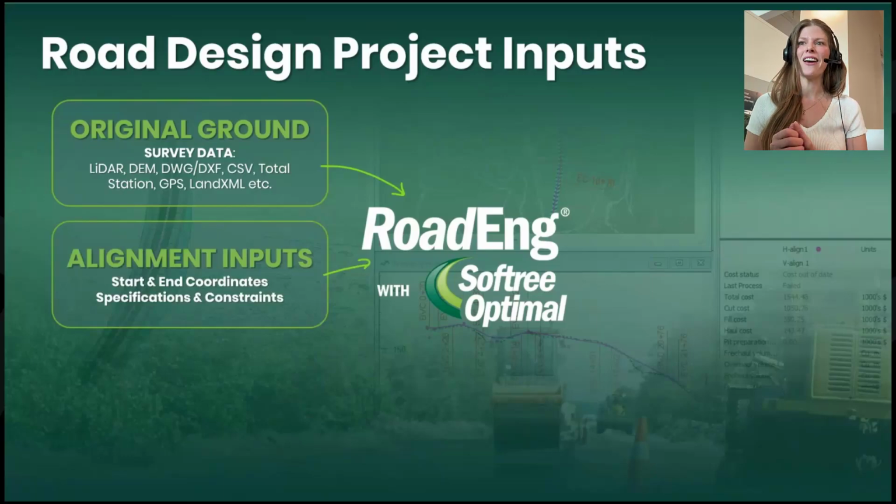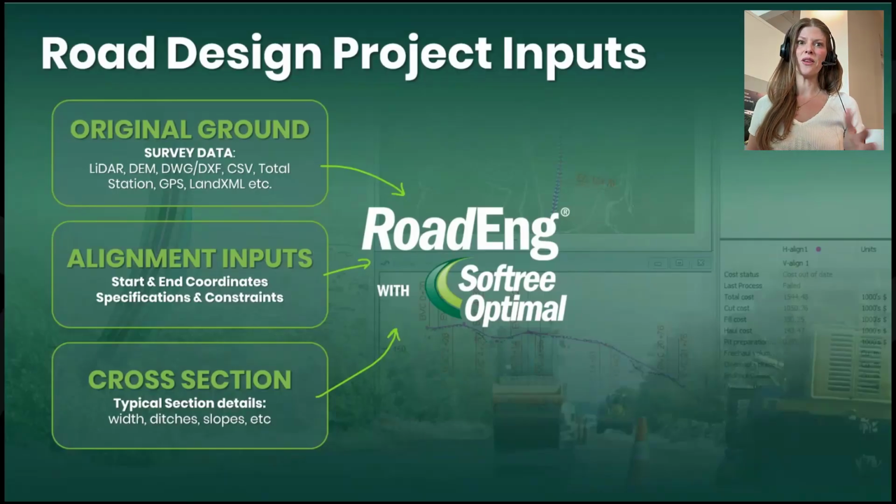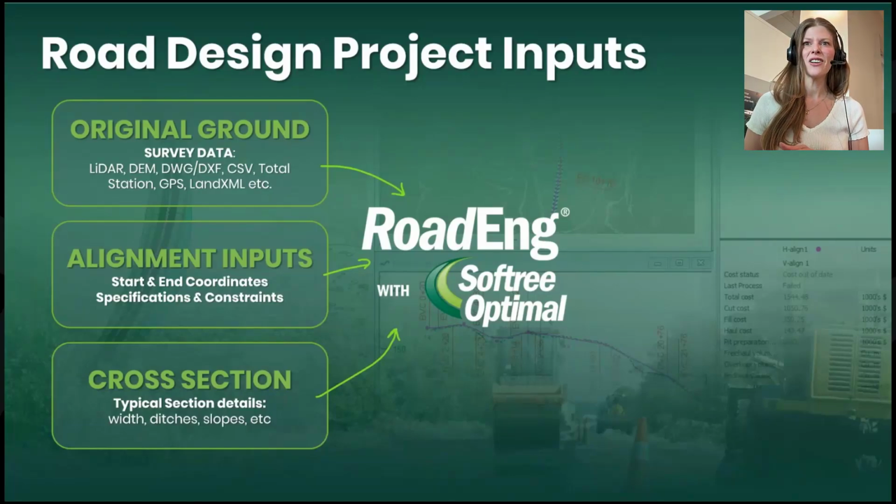From there, the next input, and this one can be as simple or as complicated as you would like to make it, but we need to know some alignment details: your start and end coordinates, some specifications, your design speed, any constraints that you might need to consider. And then lastly, you're going to need to know what your cross section looks like, whether that's a very simple trapezoidal prism with a specific width and ditches and some slopes to it, or perhaps it's much more complicated. So we're going to have those three core inputs that are going to go into RoadEng in order to allow you to do a project.